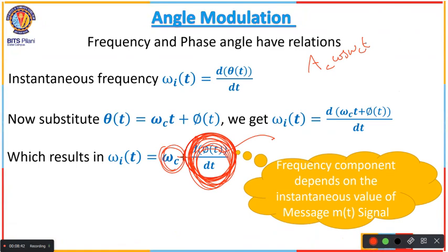This is the carrier, right? So ultimately we are transmitting the carrier only. So what did you do for the AM wave? Exactly, you are right. You made it AC plus m of t, cos of omega ct. This is for AM, right? You have exploited the amplitude of the carrier to send the signal.